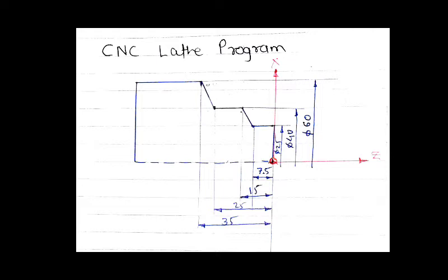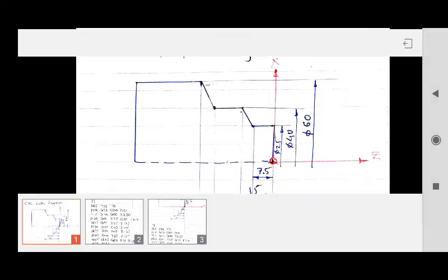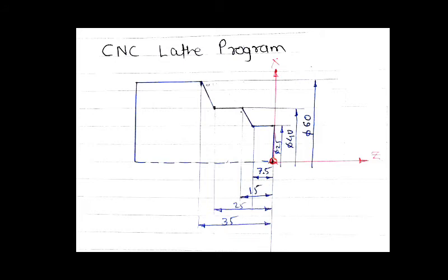First, the information needed by the CNC machine is preparatory information. Preparatory information includes units, and incremental or absolute positioning system. Then it needs the coordinates: x coordinate, y coordinate, z coordinate, rx, ry, rz. Then the machining parameters needed by CNC, that is feed rate and spindle speed.